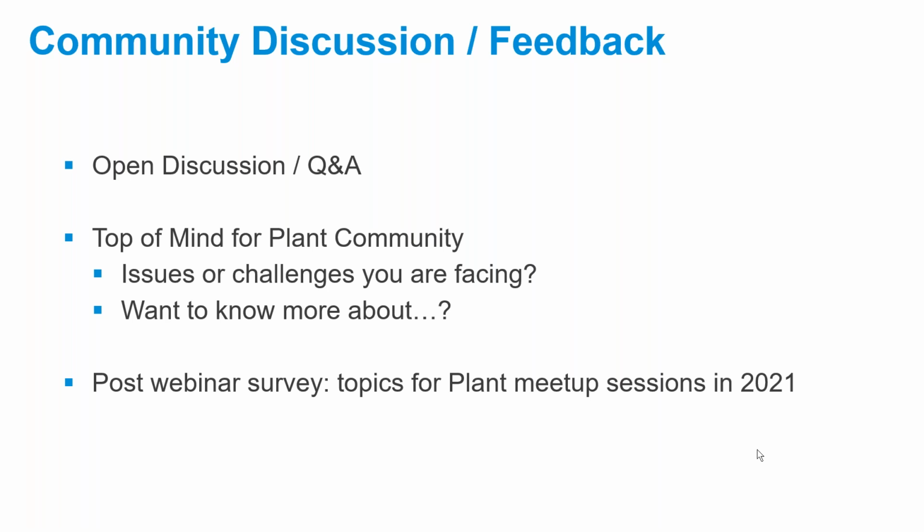So yeah, and actually we have a good input here from Alex Schmidt on the Revit workflow question that was posed earlier by Viet. He mentioned to make sure you get your Revit coordinates changed to the same as the UCS that you're using for your plant project. That way, when you're generating your exports from Revit and your views, they should line up when you bring them into either Plant 3D or Navisworks. And he's right, the shared coordinates is something you want to make sure you have aligned with your CAD or AutoCAD coordinate system, so your UCS there.